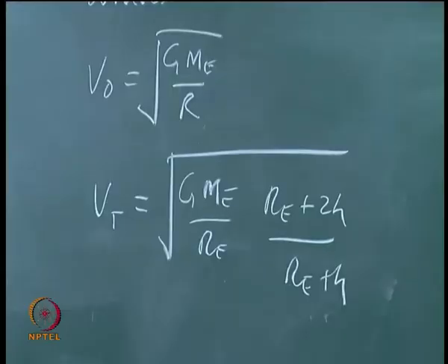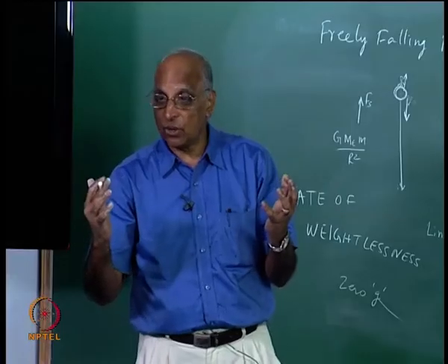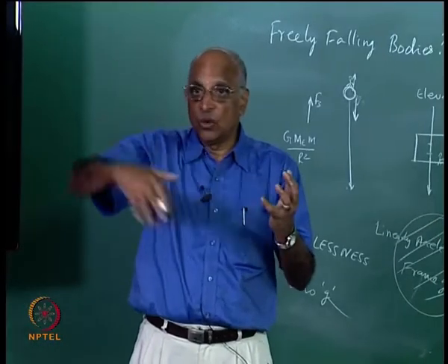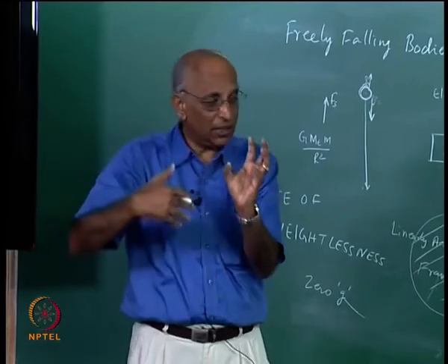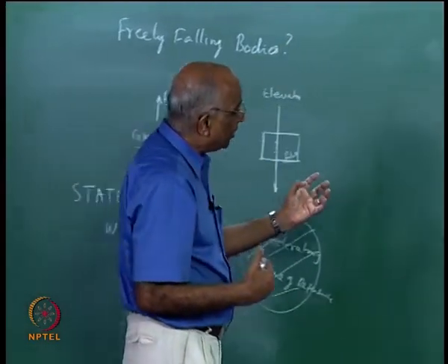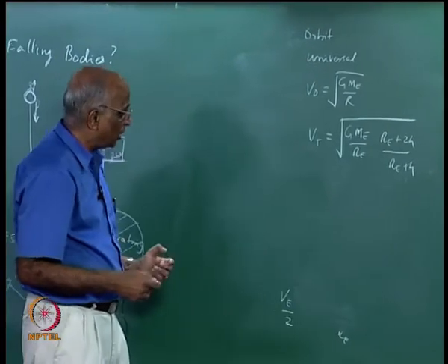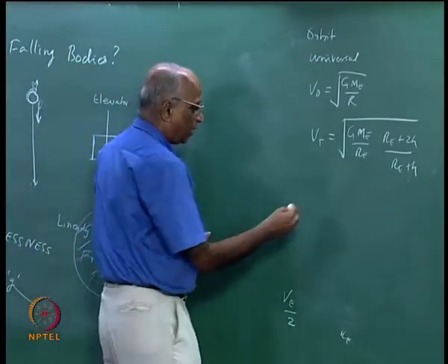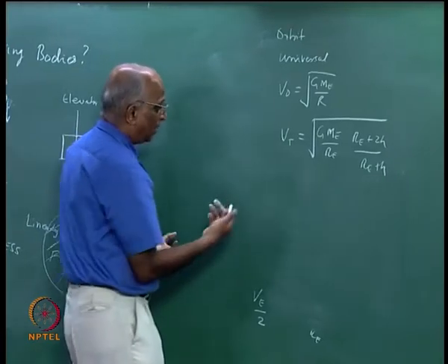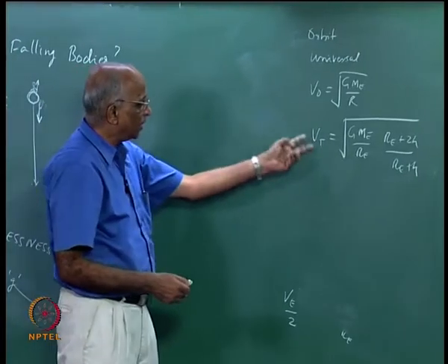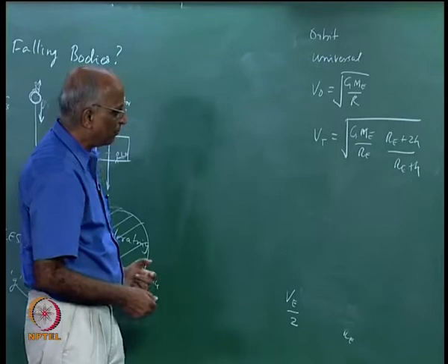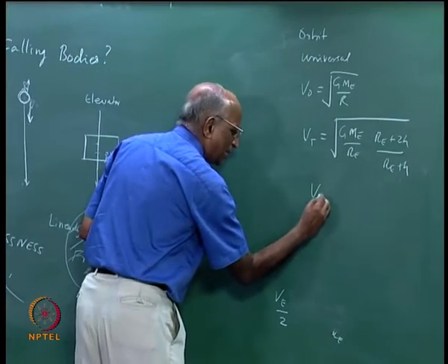We also talked of geosynchronous orbit, polar orbit. Maybe we told ourselves for remote sensing we go around so that I can see the entire earth, as it were. For communication, TV and weather predictions, maybe geosynchronous is better suited. I can also have low earth orbit around the earth at different altitudes, and we found out the total velocity requirements.